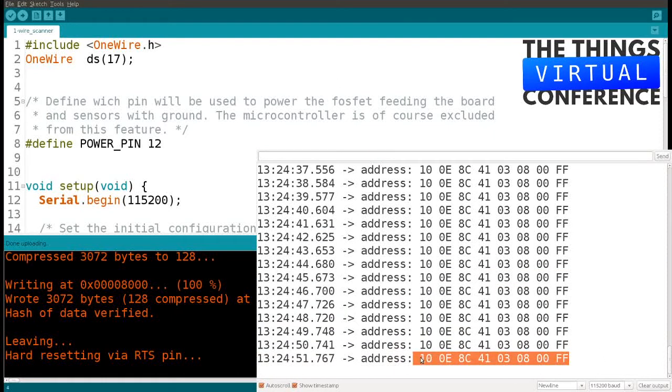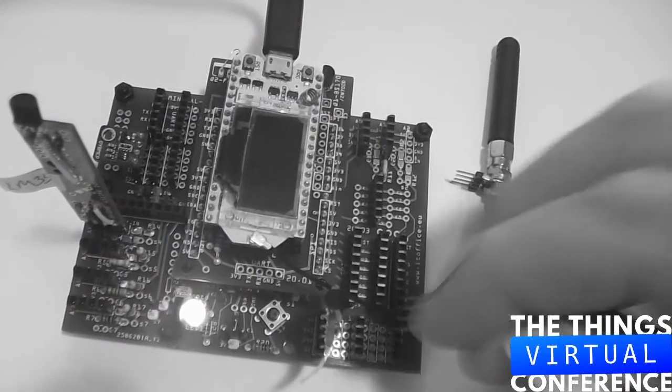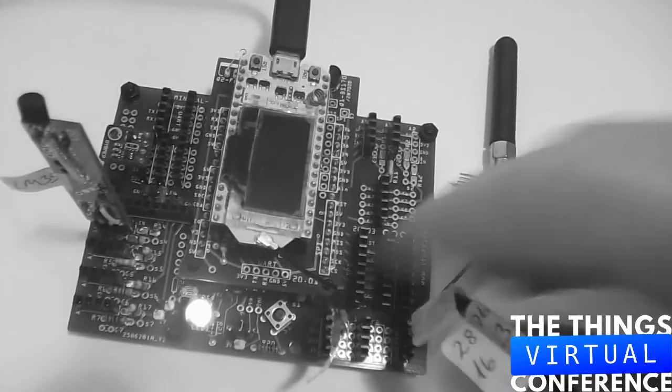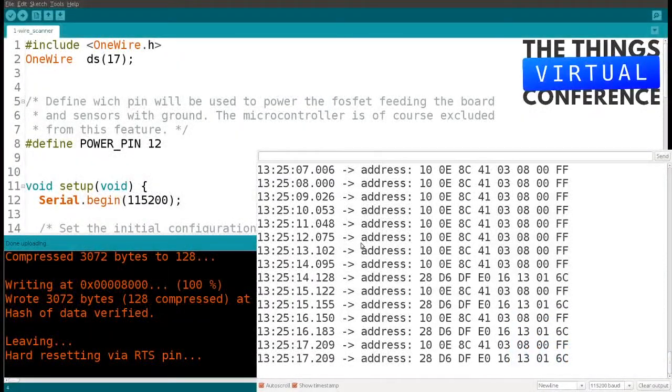This is it, 10 0E 8C, etc. That's the address. That's the only address on the one-wire bus. It scans again and again, so if I put in another sensor, it should find it. Let's try it out. Let's put it in here. Well, let's see what happens. And now I can see two sensors, two different IDs. Okay, so with this scanner software, we can find IDs. Great, that's very good.